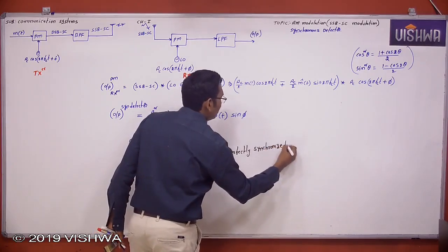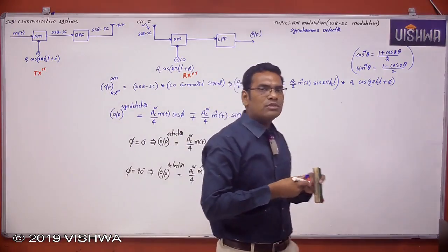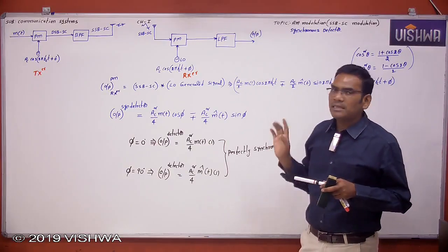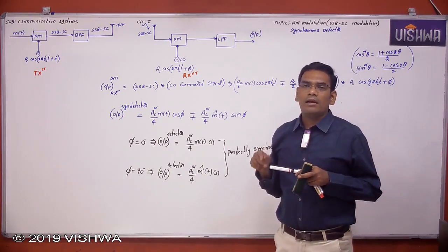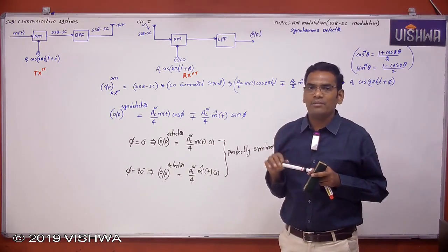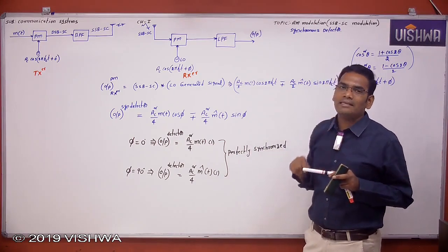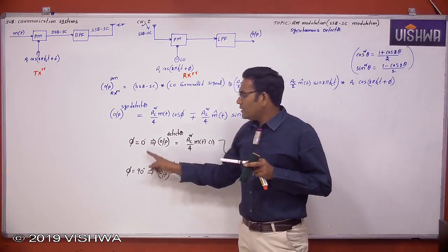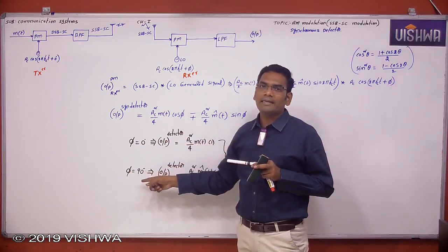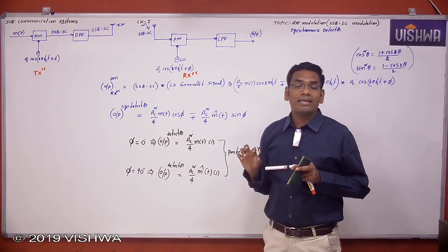What is the problem we just observed in the synchronous detector when we use it in AM and when we use it in SSB-SC? The same synchronous detector which we already used in AM and in the SSB-SC demodulator faces one common, continuous problem. When the phase is matching, it is perfectly synchronized. But when the phase is mismatched at 90 degrees and the output equals 0, that effect we call the quadrature null effect.